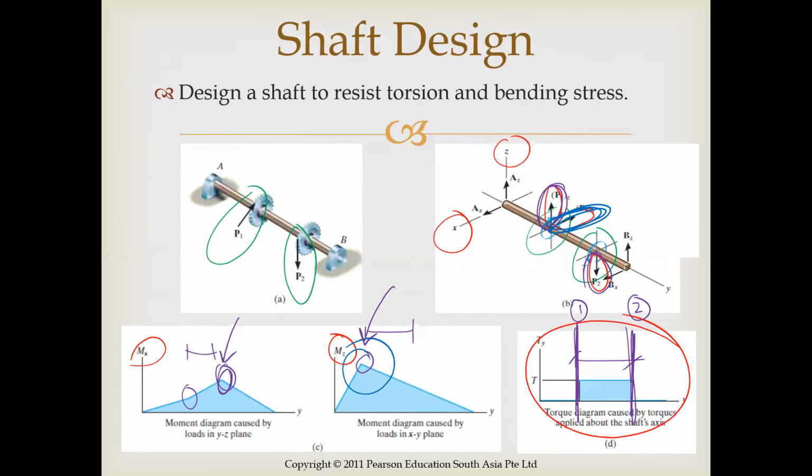He's talking about a stoplight where you have the big arm hanging over with the lights, signals. You have less moment occurring at the end. So they're optimizing the cost efficiency of that by saying at this end where we have smaller moment, we can have a tapered, smaller cross section.